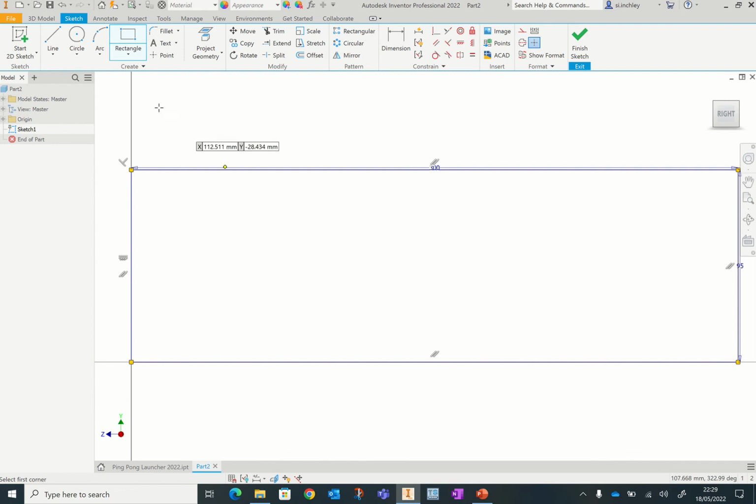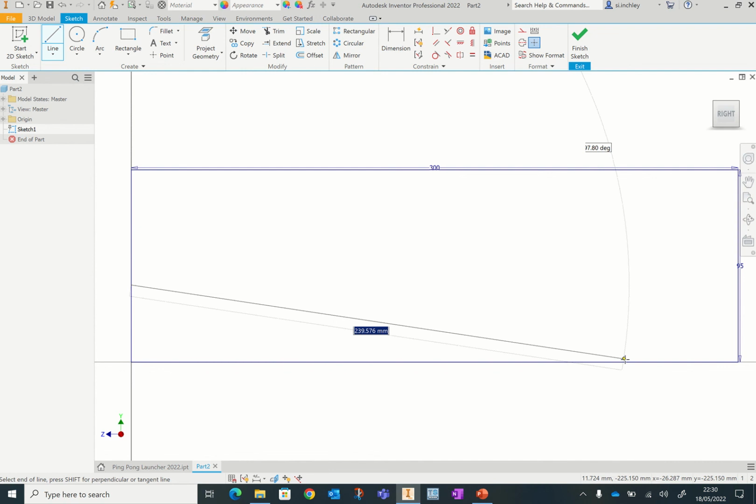So we now want to come up and select our line tool, and I'm just going to click roughly around here. Try not to click in the middle. If I hover over, see that big jump there and it gets a big dot? I'm just going to come down a little bit, so I'm not in the middle, or it locks onto the middle, and that can be problematic later. And then all the way roughly over about 3/4 of the way to here.